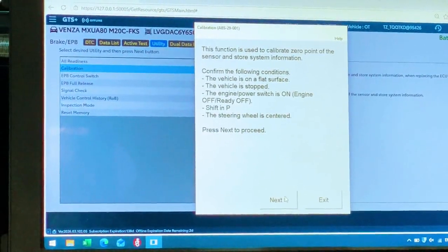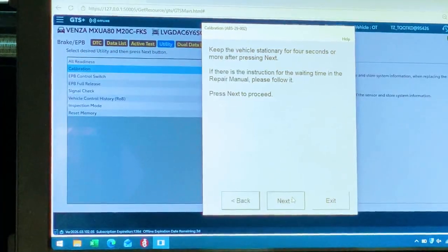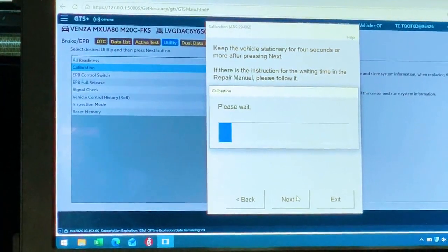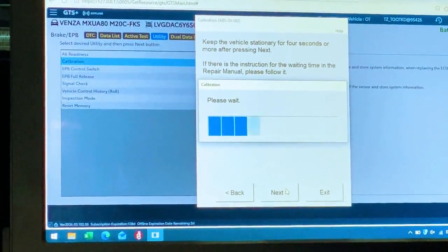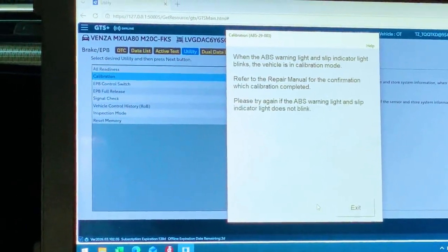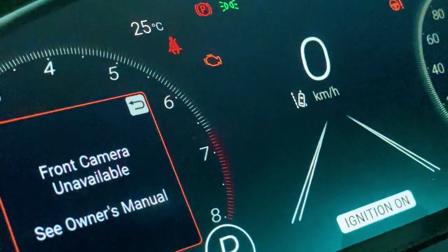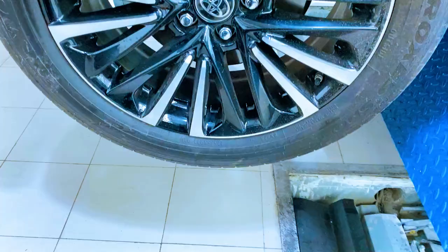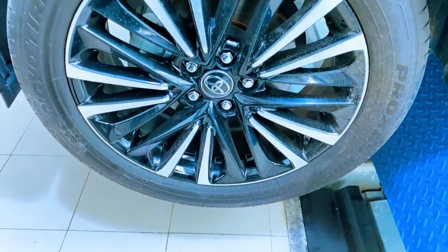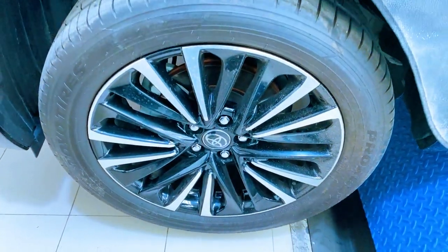10:45. Techstream initialization. Now comes one of the most important steps. Mechanical installation is not the end of the repair. Because this is an electronically controlled Toyota brake system, we need to use Techstream to perform the required inspections, initialization, learning, or calibration procedures for the specific vehicle.